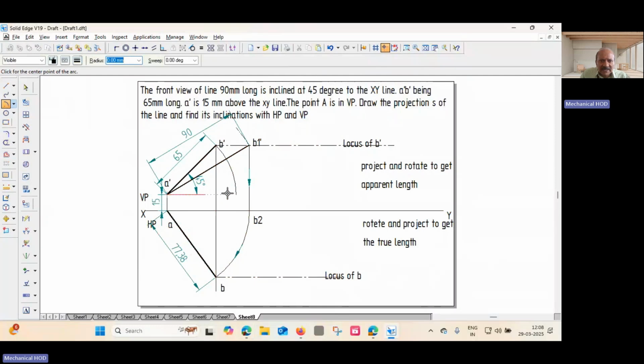So here, this line I will extend like this. There is a command adjacent to the trim command. Click on the triangle. There is a command called extend to next. Click on that. You can read here, click on the element to extend. I want this line to extend. See how it is extending. Extend, extend, again extend. So it will extend up to there. Let us call this point B dash. Let us call this point B2 dash.